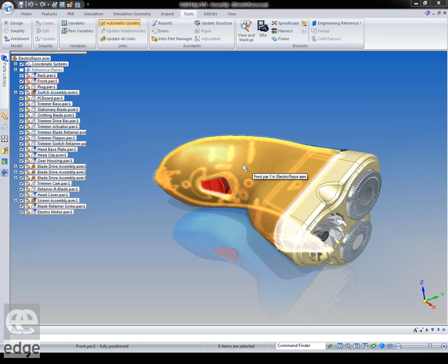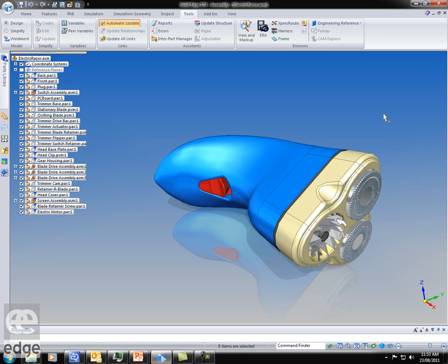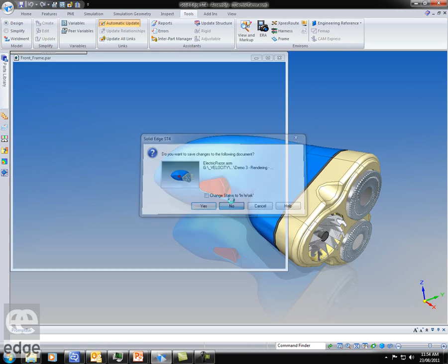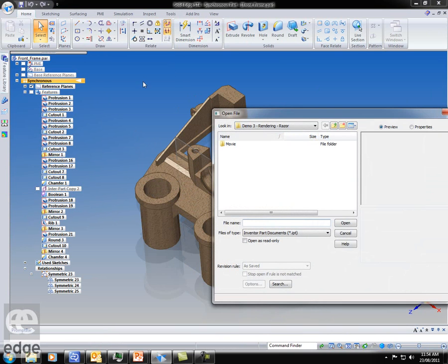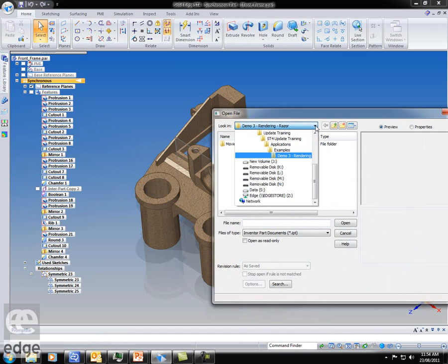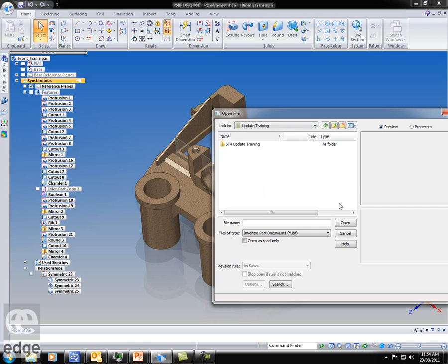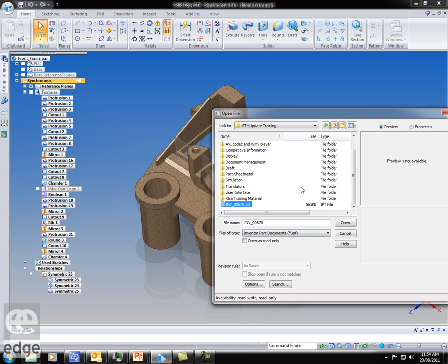It's nice, but it's PDF. Let's convert the Inventor file, and you'll just get a feel for that. So it's an open. We want to open here, and it's in there, I think. There it is, an IPT file, so we can open parts and assemblies. It'll automatically translate them into Solid Edge.